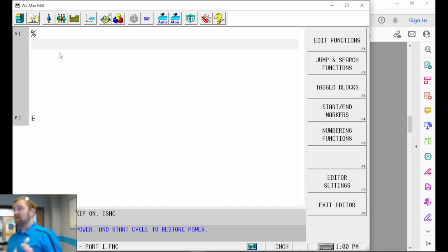If we put, and I do need to make this really clear, if you put the percent sign at the top and then you forget the one at the end, when you go to open your program, you're going to freak out because it's not going to show you anything. It's going to look like there's nothing there. Don't worry. Say, hey, I know this program is here when I hit save and now it's blank. Let me know. I'll come fix it. We have to open it up in a text editor and add that extra percent sign that's missing.